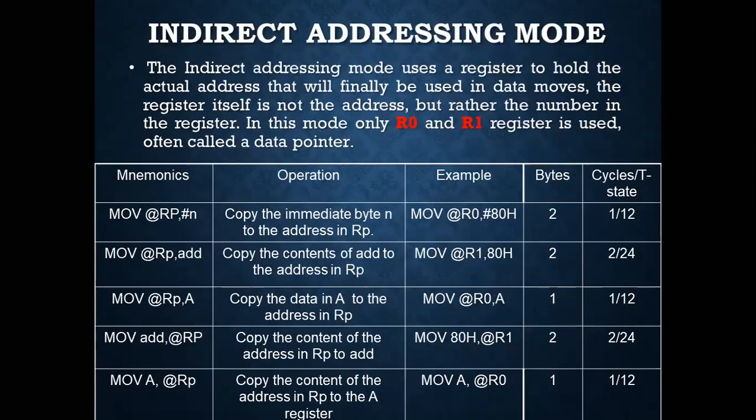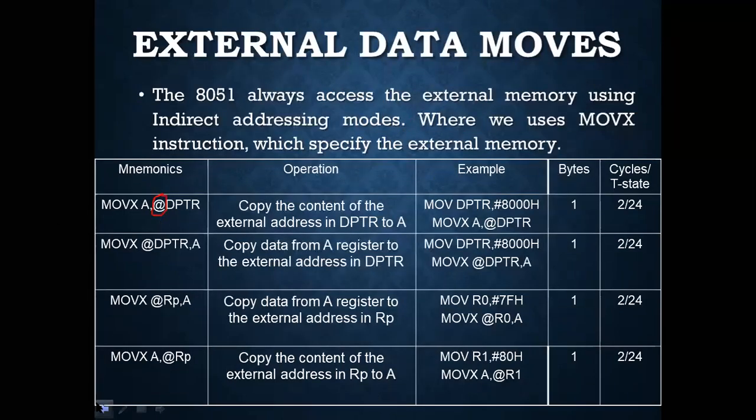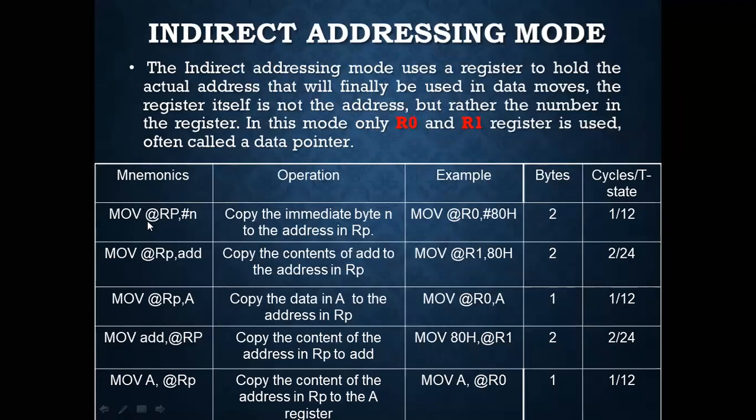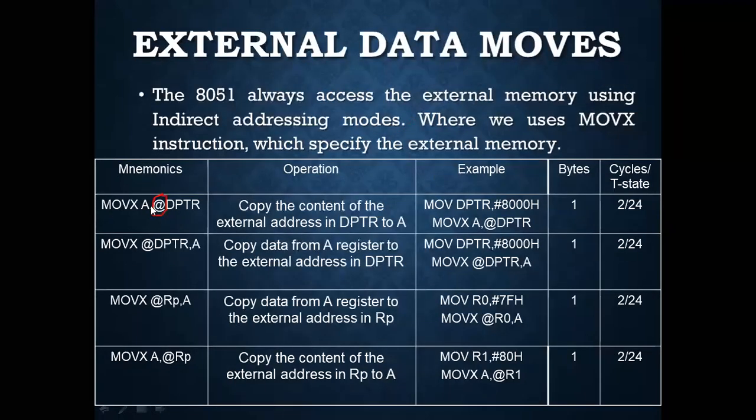Just like in the previous one we discussed with Rp, @Rp means whatever the content of the Rp, that will act as an address. So here also the DPTR is storing some 16-bit data, and this 16-bit data is acting as the address.